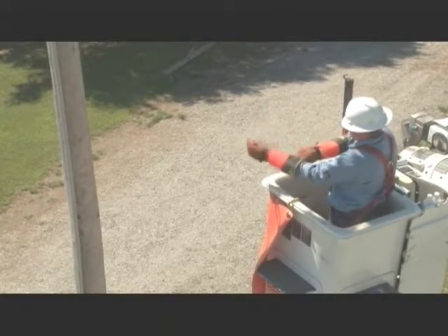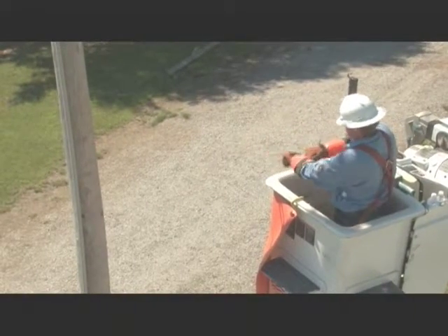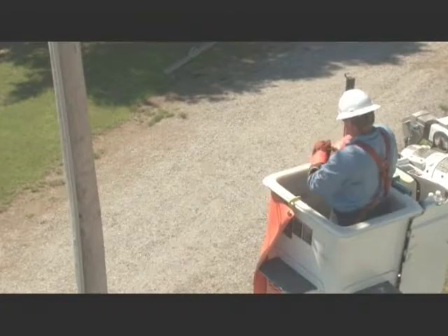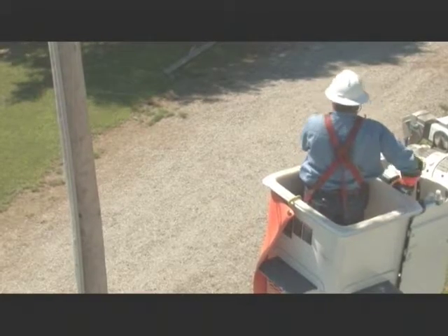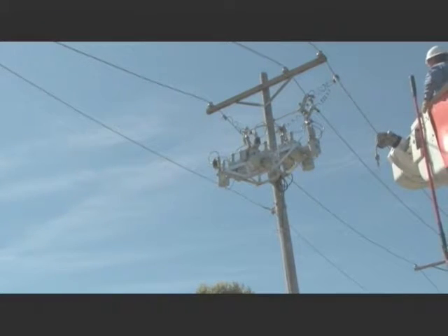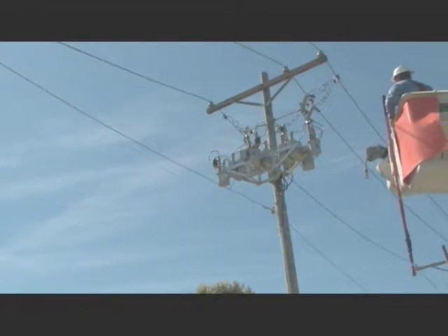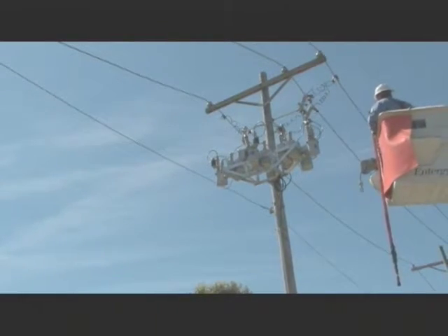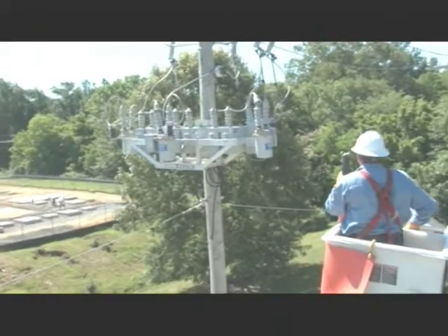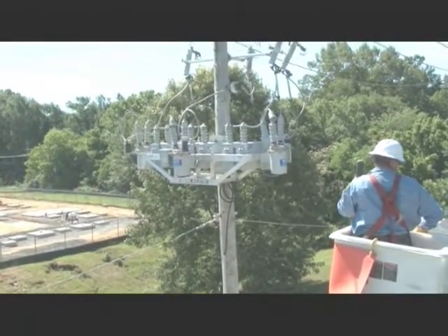In this inspection, he checks for any sign of discoloration or corrosion that would indicate that the units have overheated or have been damaged. In addition, he also inspects the tanks of each unit for obvious signs that they're defective. For instance, he looks for any signs of an oil leak or for sides that are bulging out on any of the tanks.